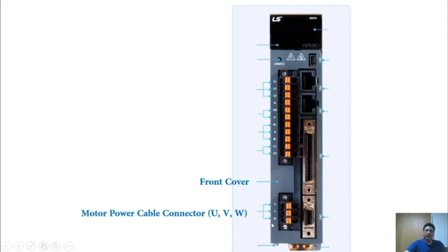An important point to keep in mind is that the U, V, and W marked on the motor must be connected exactly to the U, V, and W on the drive, with each one installed in its correct place. If we connect these terminals in reverse, it can cause damage to our motor because these terminals are designed to be connected in a specific order to ensure the motor operates correctly. Reversing them may result in the motor running in the wrong direction or even cause internal damage.